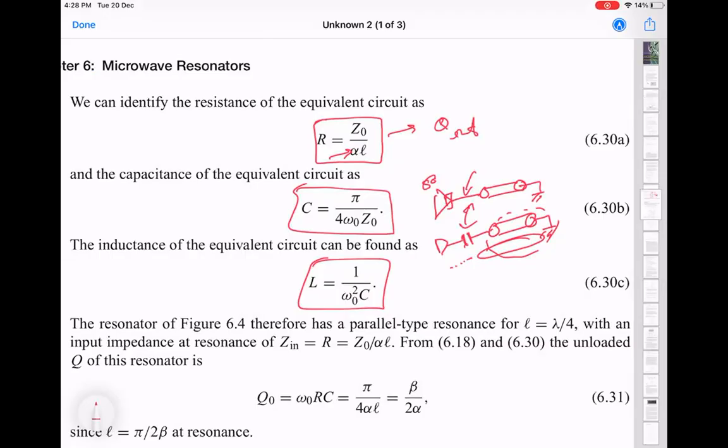So maybe let me repeat that for a few minutes. Why is that? It's because the size of the inductor which you build is going to become comparable to the wavelength. How does one make an inductor? Typically, you coil some wire. You have seen in your undergraduate labs those big wire coils. That's because you are making inductors whose values are in microhenry and maybe even millihenry. But you completely forget the fact that between two rounds or two windings of the wire, there is actually going to be a capacitance between those two. That is completely not modeled in your analysis because the frequency is so low and the capacitance is so small that 1 over omega C is essentially infinite.